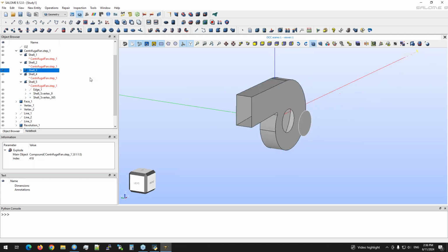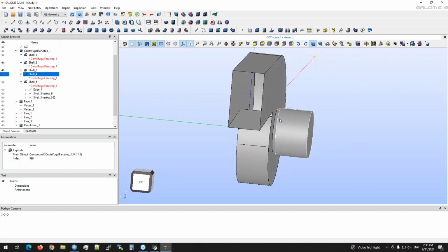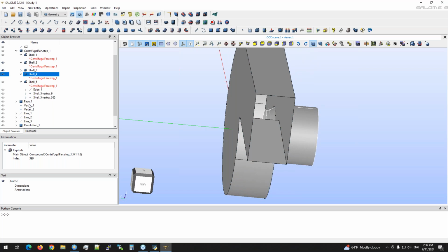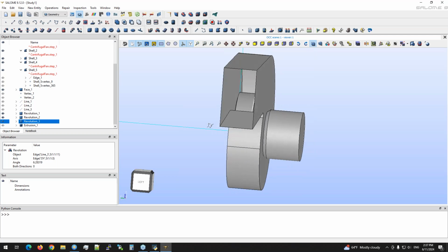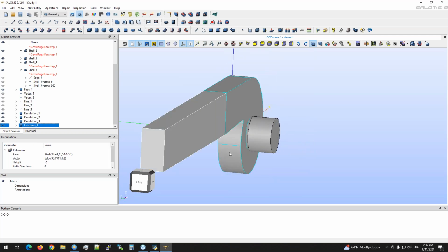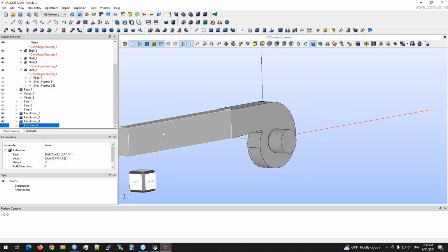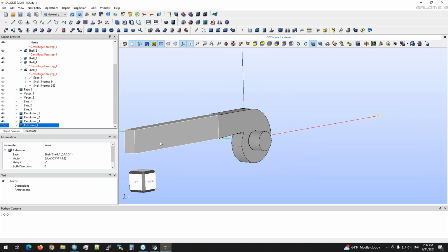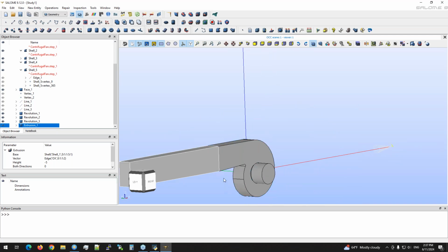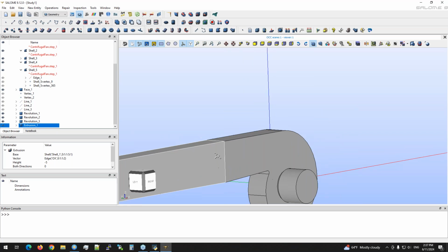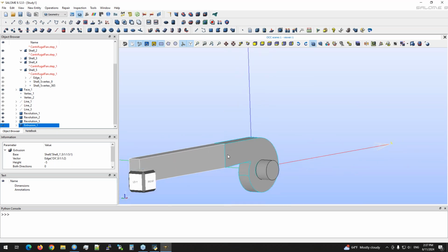Then we need to add, of course, the inlet. Then we have the suction wall, let's say the suction part. Then we will add the interface here. We will add the impeller itself, the outlet interface we made, and I think the last one is the extrusion, because it also includes the interface. So we can set this extension as a separate part, because then we can set the evaluation, for example, directly at this interface for efficiency evaluation or pressure drop, because we have some kind of measurements at these positions.